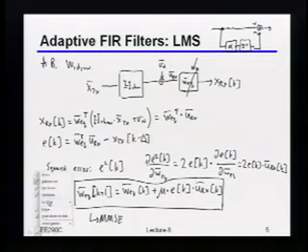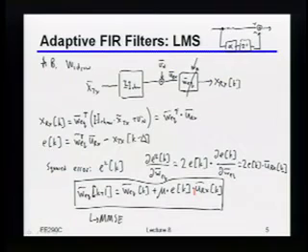So when I do this update equation over here, I really just have one coefficient, which is this alpha value. But in order to find that alpha value, what I really have to do is correlate the current error with essentially what came into the equalizer 1 bit ago. Does that make sense now?